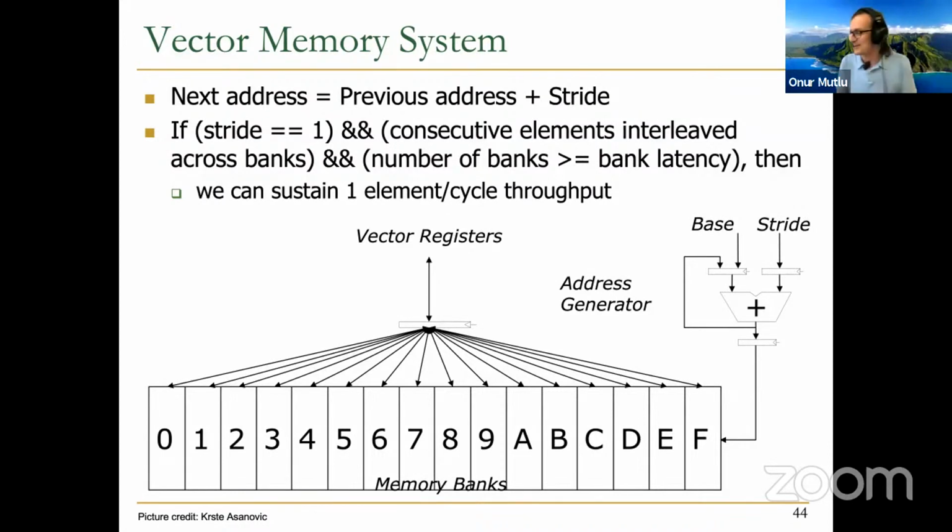For a mathematician, the answer is 33, absolutely, because you only need 33, right? But then how do you address that? Because we have binary numbers. Addressing an odd or a non-power of 2 location in memory or bank number is not easy, because we're going to use the address to determine which bank to go to. Some bits in the address will be used to essentially decide which bank that address maps to, right? The bottom bits after the word, in our case, because consecutive elements are interleaved consecutively. But basically, 33 is difficult to build. That's why we go to the next power of 2, which is 64, right?